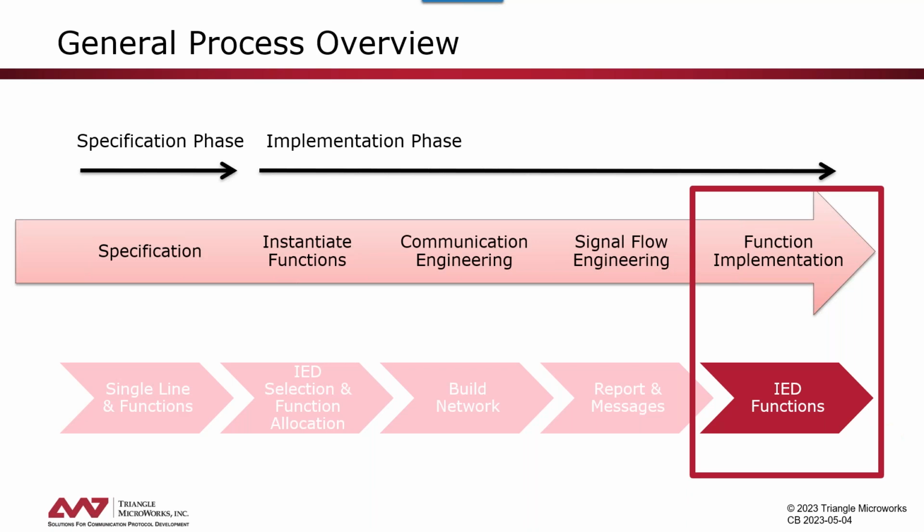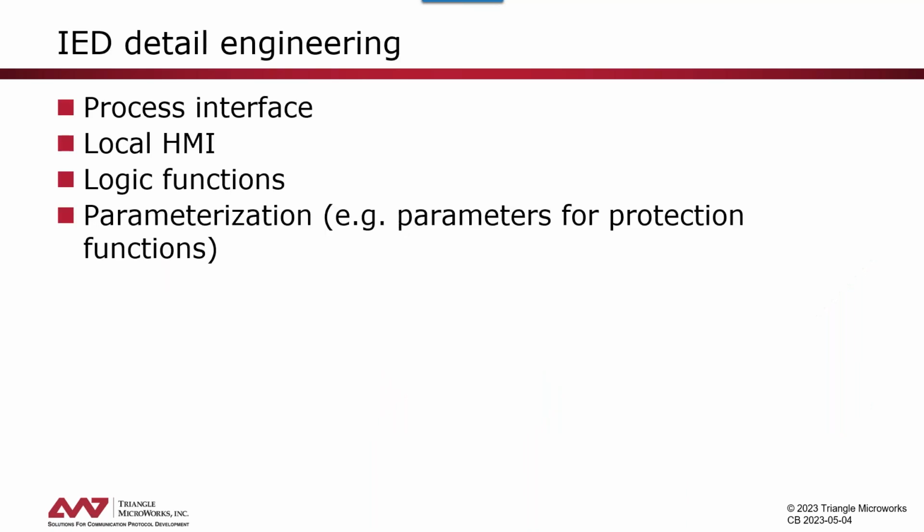So now we are more or less getting to the end of our engineering process. With this, we have to implement what we have defined in the system tool in the different IEDs. So for that, the IED specific tool imports the SCD file, but then we have to do some specific configuration, which is IED specific, which is not yet necessarily standardized. That's why it has to be done on the IED tool.